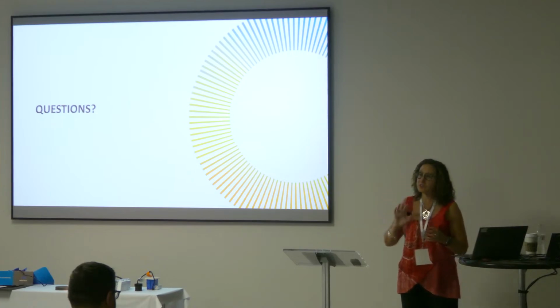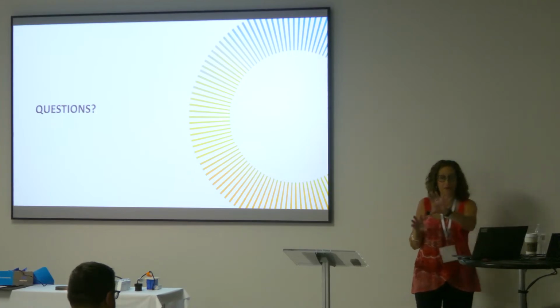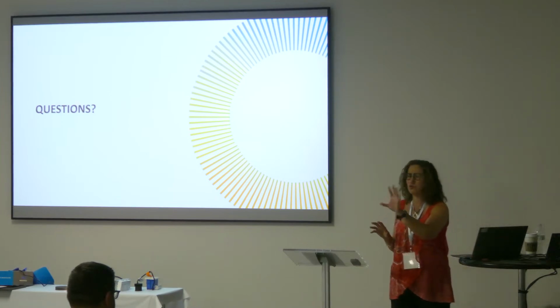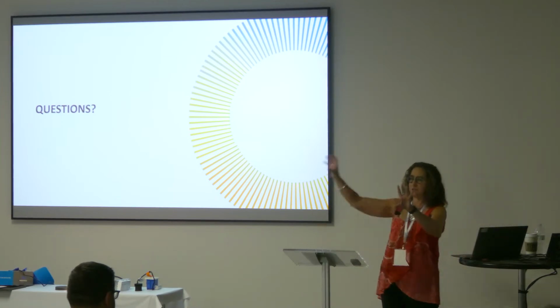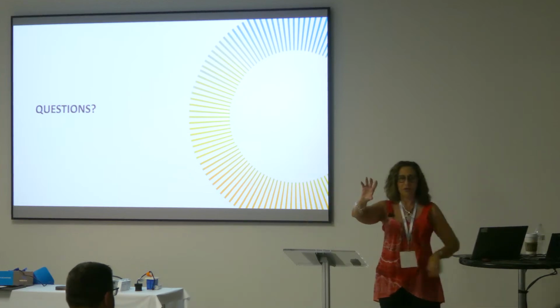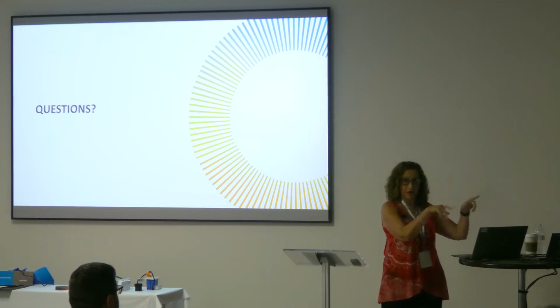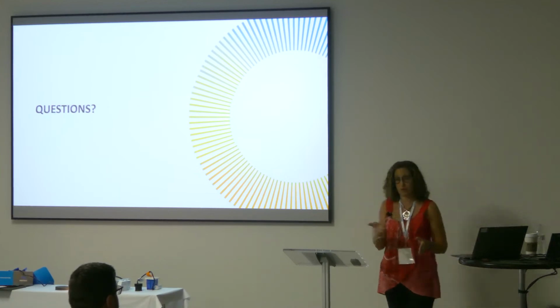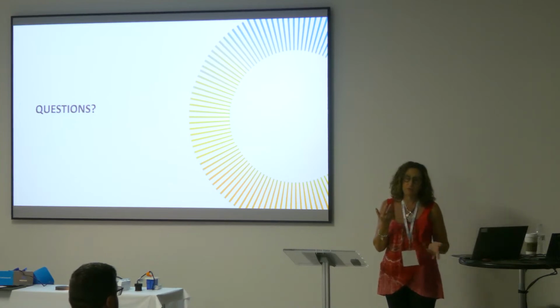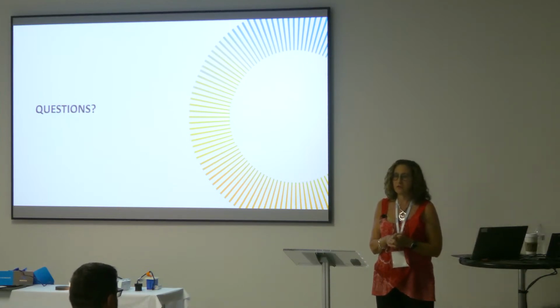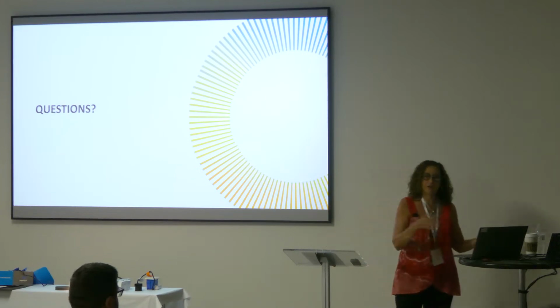Yeah. It's problematic. So you can, for example, take the Acuity one or the Cooper one, and you could bring something in. Like you could bring a Wattstopper system in that spoke DALI, and a Cooper system in that spoke DALI, and there might be some conflict-y thing, but you could figure it out. As long as they can both take a BACnet gateway, you could figure out a way to make the two systems work. That other system, the big L guy, never. It's a closed loop. You can't get in there, and they do that for commercial reasons, and I find that problematic. It's because DALI is an international open protocol, and they don't want that.